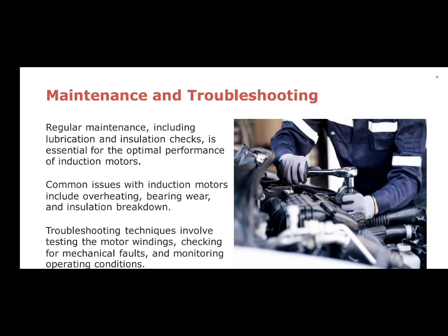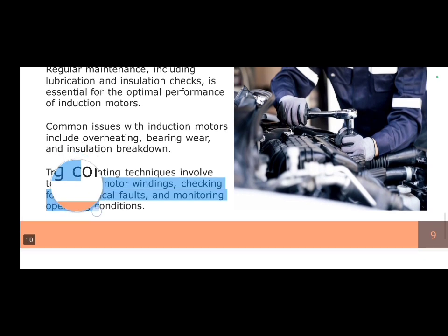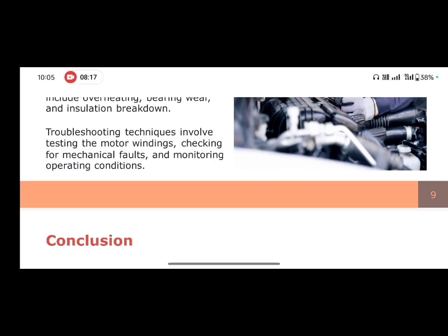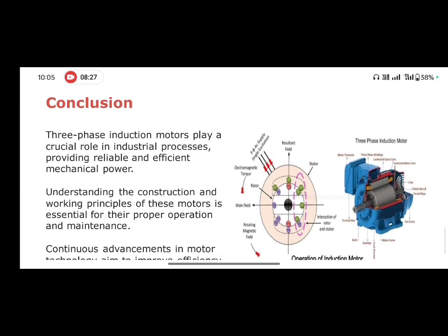now let us understand maintenance and troubleshooting. Regular maintenance, including lubrication and insulation checks, is essential for optimal performance of induction motors. Common issues with induction motors include overheating, bearing wear, and insulation breakdown. Troubleshooting techniques involve testing the motor windings, checking for mechanical faults, and monitoring operating conditions.